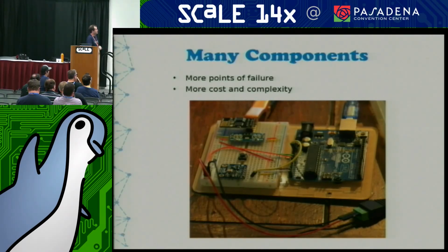So the other thing about the first way that I was doing it is you have many components. So I showed you the voltage regulator. Well, I got one off eBay that's kind of an all-in-one. It's got a built-in kind of heat sink and way to deliver clean power. It's not as physical mechanical. It's got some smarts to it, so it's a better tool to use. However, it's not reliable. I've killed 2 of these things. Likewise, you have to have a switch to do the programming of the ESP8266. I'm showing this with an Arduino, but that's not really involved in this.